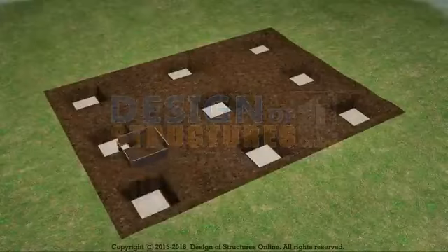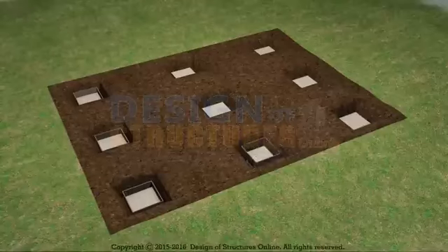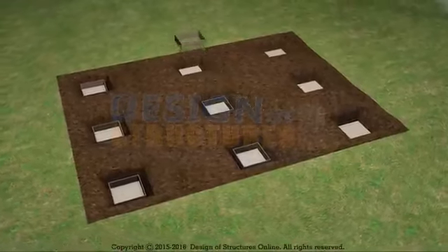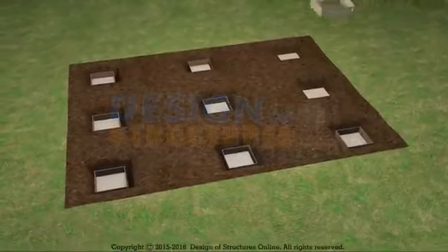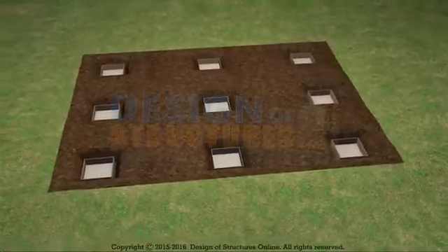Foundation shuttering. Shuttering arrangement for the foundation is to be made. Once PCC is done, shuttering for the foundation is placed. It should be strong enough to withstand all types of dead and live loads.